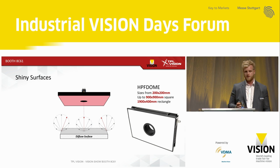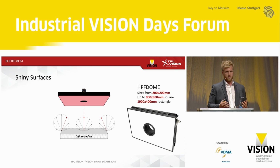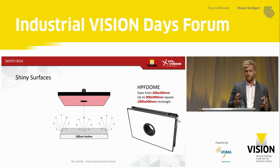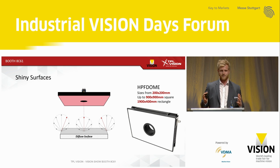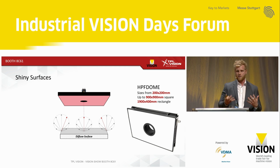Another problem, which is a really common vision problem, is shiny surfaces. Now, if you think about the way that the light reflects when you hit something diffused, like how I showed you before, that's called your Lambertian distribution, which is the way that the light reflects off the surface. It's really hard to quantify because it really depends on the surface that you're inspecting. This is really the reason why in all vision applications you always have to test your product, because it's really an unknown number how much the light will reflect.